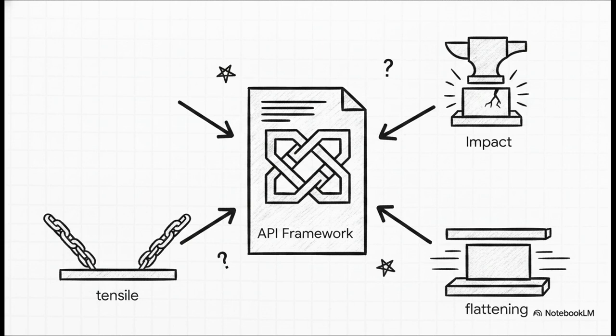Instead, it rigidly points you straight towards specific ISO and ASTM standards to carry out the physical drops, pulls, and crushes. Tensile testing? Go look at ISO 6892-1 or ASTM A370. Charpy Impact? ASTM A370 or ISO 148-1. API gives you the ultra-strict framework for when and where to test, but it relies entirely on these globally harmonized engineering standards to dictate exactly how the machines operate. It's a massive collaborative effort.